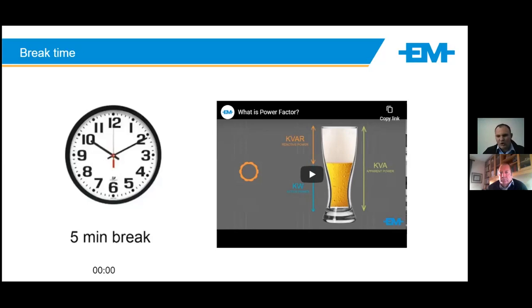Depending on how hard it needs to work, it might be exceeding its standard or manufacturer limits. You could see that very easily if you bring in a capacitor, say it's 25 kVAr, and you measure the line current and compare it to what the manufacturer says it should be. If it's higher, then there's an immediate sign that something's going on here, and then you need to do the logging.